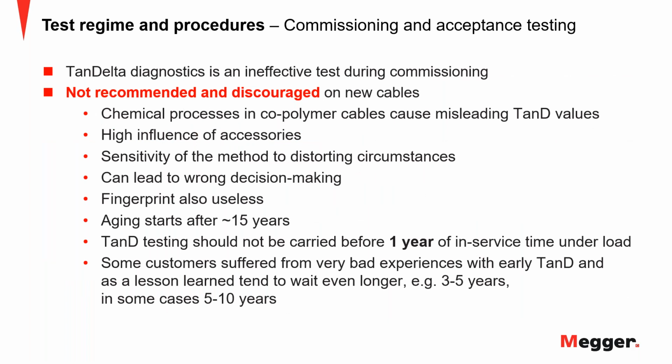Now, in terms of global issues, we talked about these, the insulation is still there, right? That's the actual cable. Just to have something said about the tan delta test here. On new cable, we're still talking about commissioning cable here, acceptance testing. It is not recommended at all and discouraged actually to do a tan delta test on new cable.